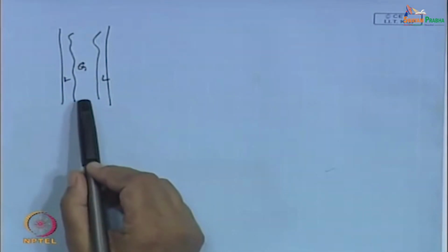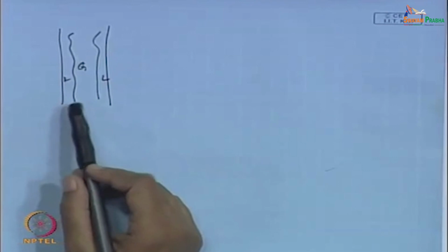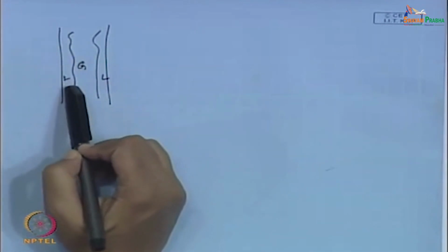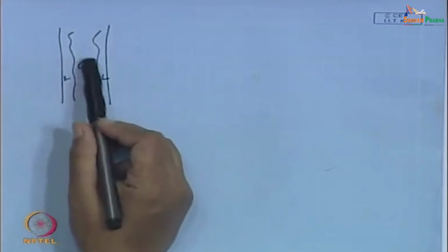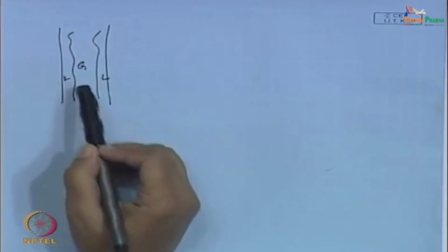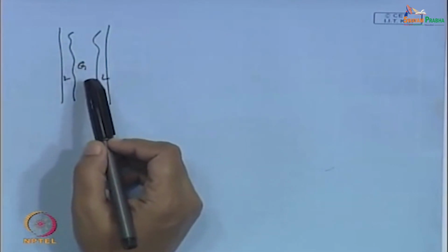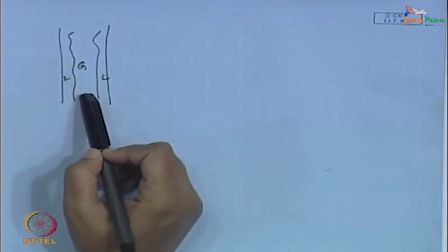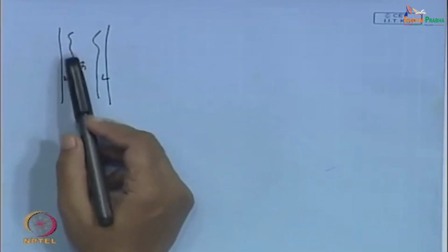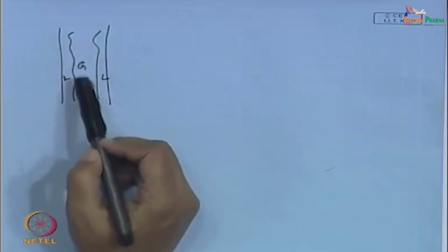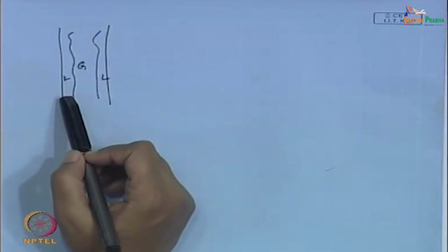If we keep on increasing the gas flow rate and decreasing the liquid flow rate, under unheated conditions, the liquid film becomes thinner and thinner, the interface becomes smoother, and the gas core becomes thicker, but nevertheless there would be an annular flow pattern. As we go for higher gas and lower liquid, when the slip is very high, we get a smoother interface, and therefore we do not get anything beyond the annular flow pattern.